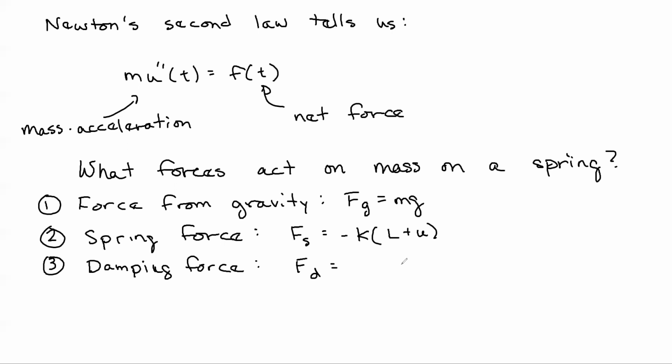All right, and what is that? That is going to be the damping force. The way that it works is that it applies a force that's opposite motion. So motion is a velocity. So we have a damping constant times the velocity.